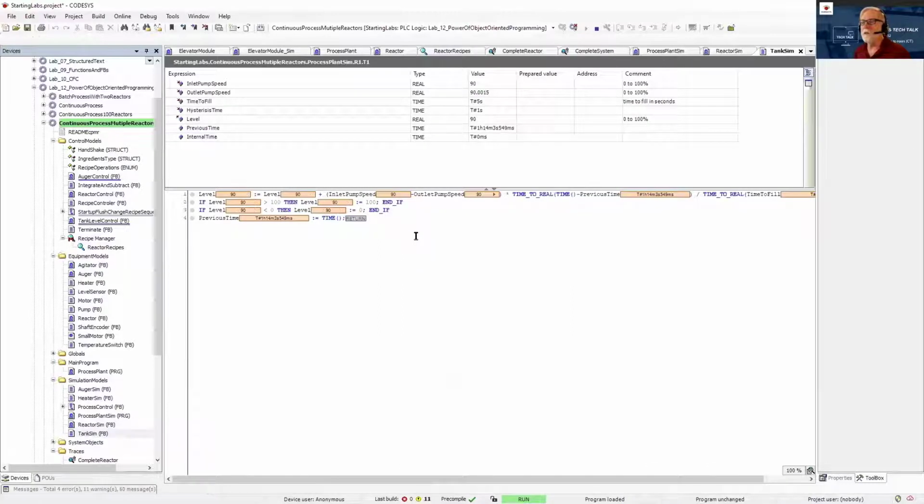What does the tank simulator look like? It's 4 lines of code. The tank is an integrator, right? So you have to integrate, remember your calculus. So the current level is the old level plus the difference in flow, the inlet flow minus the outlet flow, times dt. That's it. Then we do a little clamping here so we don't overflow or underflow. Normally I'd put a pop-up error here if the tank overflowed or ran dry, but just for simplicity, that's all we've got here.